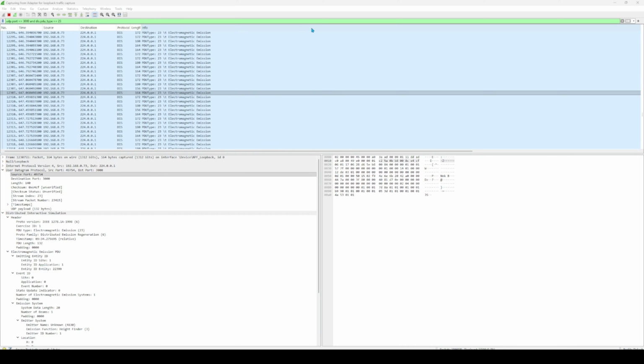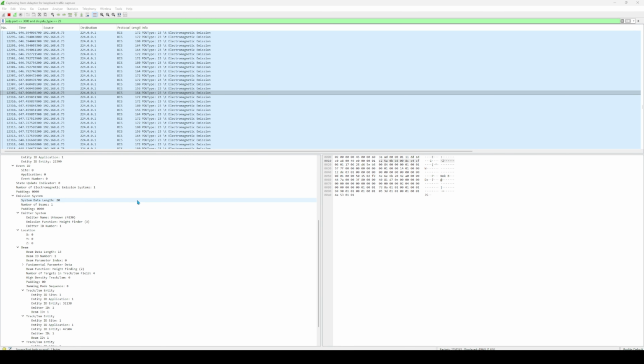Now, if we change the search filter to Emission PDU, the Emission PDU is what makes Clearance useful to an ELINT or radar warning receiver federate. It broadcasts my radar fingerprint: center frequency, pulse repetition frequency, pulse width, effective radiated power, and the emitter catalog code. 9.5 GHz, 1 kHz PRF, and 1 microsecond pulse. That's how a receiver classifies the radar type.